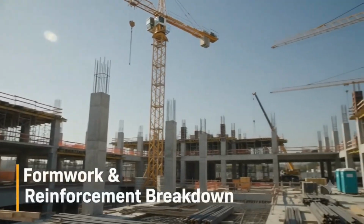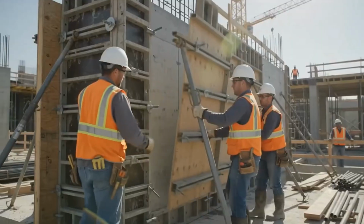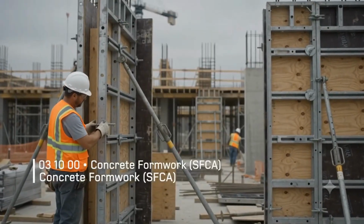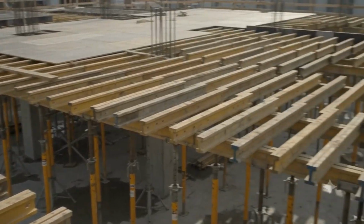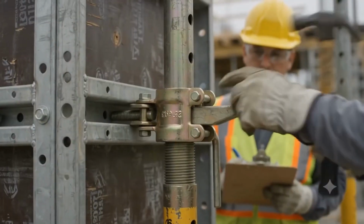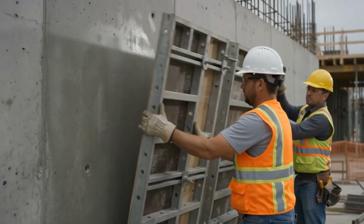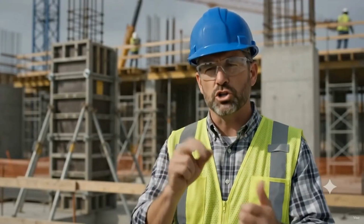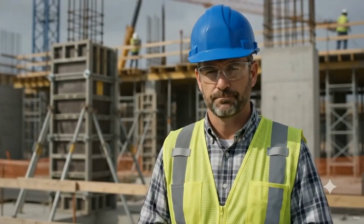Let's break down the 2 critical structural subcategories of Division 03. Section 0310 covers formwork, measured in square feet of contact area, slab shores, column clamps, release agents, and form reuse factors. Remember, formwork can represent up to 50% of your total structural labor cost.